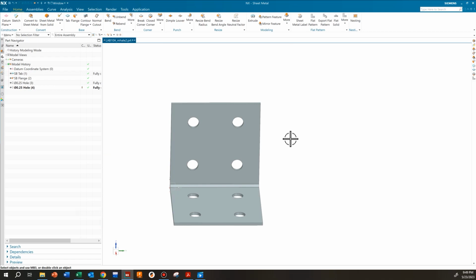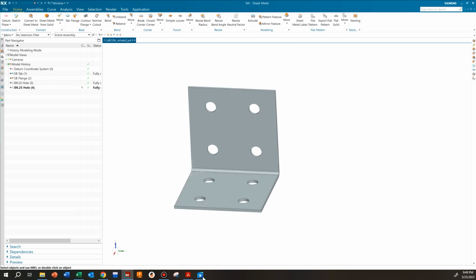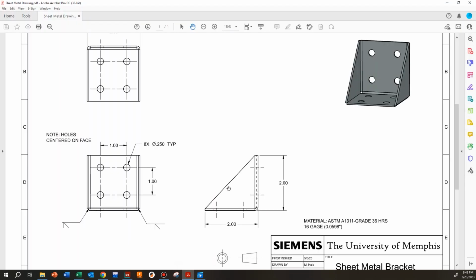Make the holes. We've got our 8 holes. Now we can start working on these triangular pieces that are coming into our bracket. Now, the bracket, what'll happen is once we make the bends, we have got 3 bends here. We've got 1 at this bottom corner, and then we've got 2 on the side. And once we have those bent, we can then lay down a weld on the 2 edges and have a solid bracket. So sheet metal and welding kind of go hand in hand for a lot of different projects.